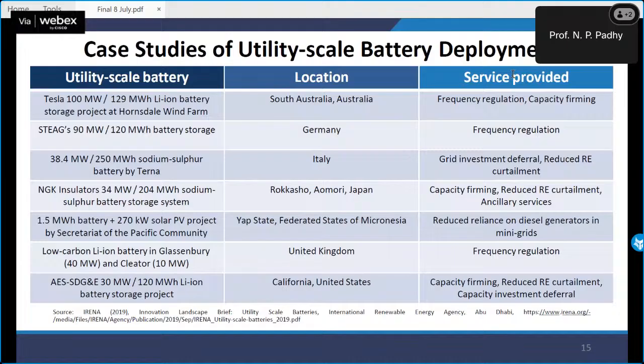You got my point? So this 90 megawatt is basically the capacity, and 180 megawatt hour is the total energy that can dissipate from the complete energy pack. All right. So the moment I say 90 megawatt and 180 megawatt hour, what does it mean? So 90 megawatt in hour 1, another 90 megawatt in hour 2.